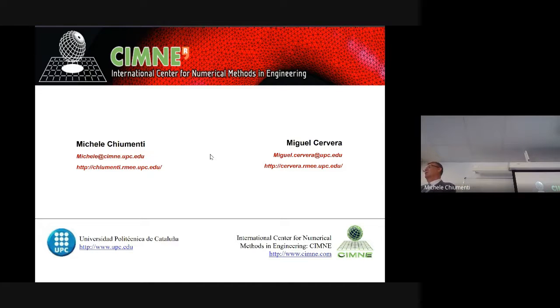I would have one question about size effect. So you said that the nominal strength will be lower for larger specimen size. Yes. But is it due to the effect of the stress concentration? If I would have a homogeneous bar and just increase the size, so no notches or anything, I find it a bit difficult to imagine that the peak strength would be different, because we always input the strength as a kind of parameter.